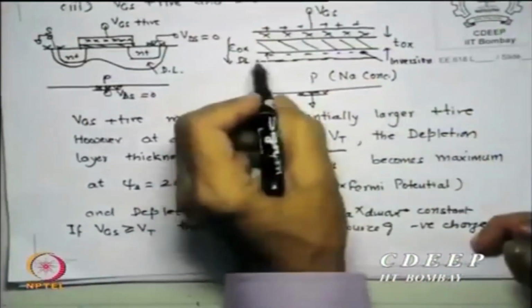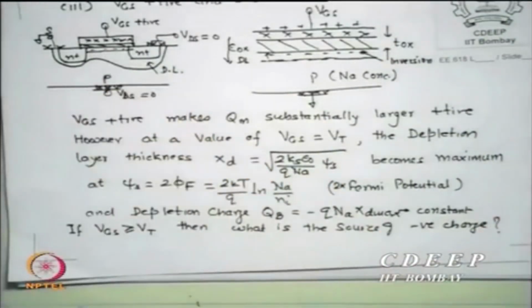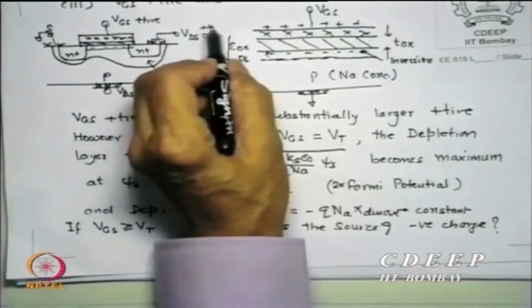So the way a MOS capacitor works, and therefore a MOS transistor works, is that there is a threshold voltage at which this can occur. Is that correct? As I said in this figure, this channel can be created somewhere here, if VGS is positive like this and VDS is also positive.